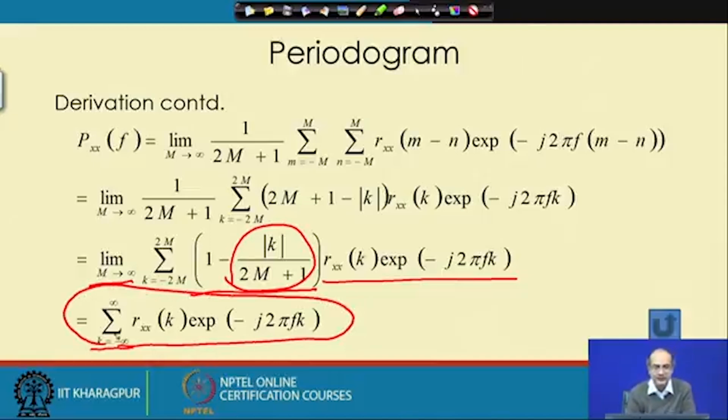So, what we get, that the expression what we have derived for our case, that periodogram, that is nothing but a new way to find out our PSD without directly going to get the autocorrelation function and then going to compute the frequency domain transform to get the PSD.